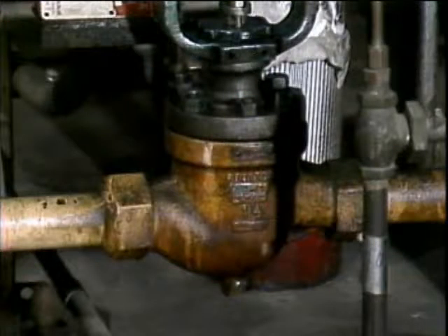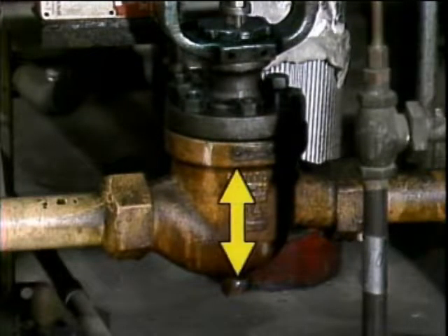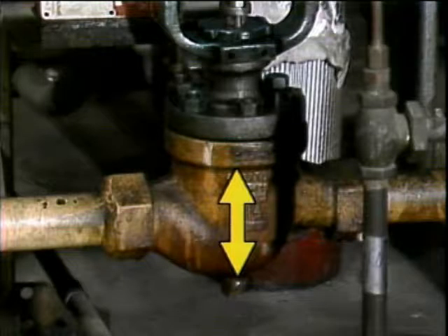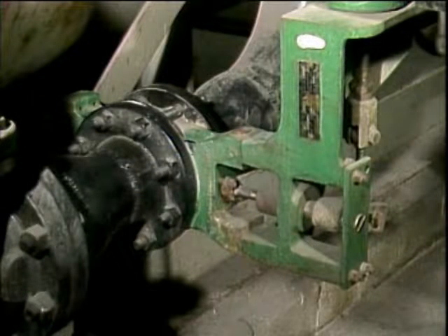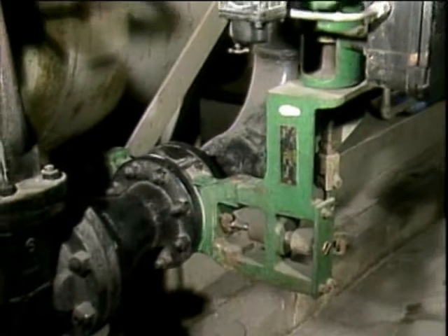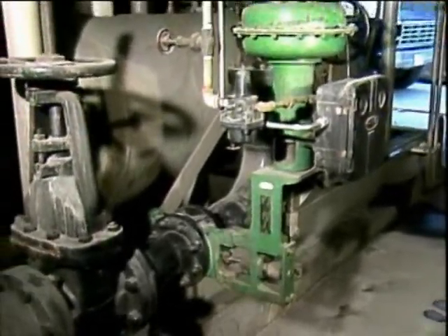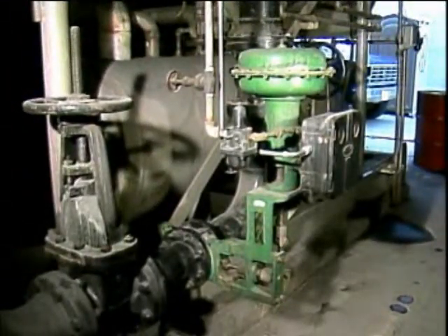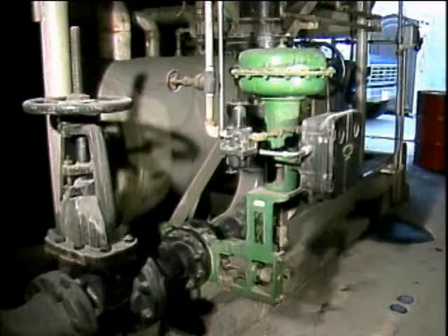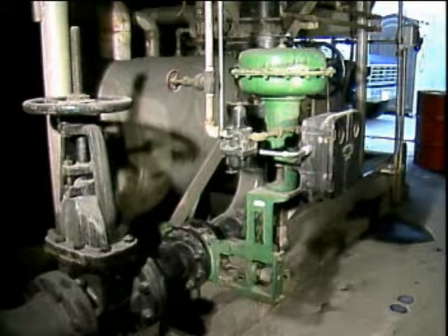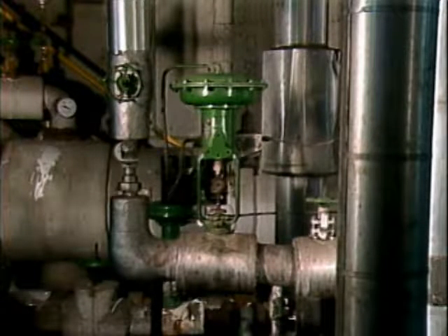Control valves can be either linear, that is, the stem moves the valve disc up and down, as in globe valves, or they can be rotary, which means that they're positioned by rotation. Butterfly valves, which open or close with a 90-degree turn, are examples of rotary control valves. One of the most common types of pneumatic actuators is the diaphragm actuator. In a diaphragm actuator, air pressure acts on a flexible diaphragm to position a valve.